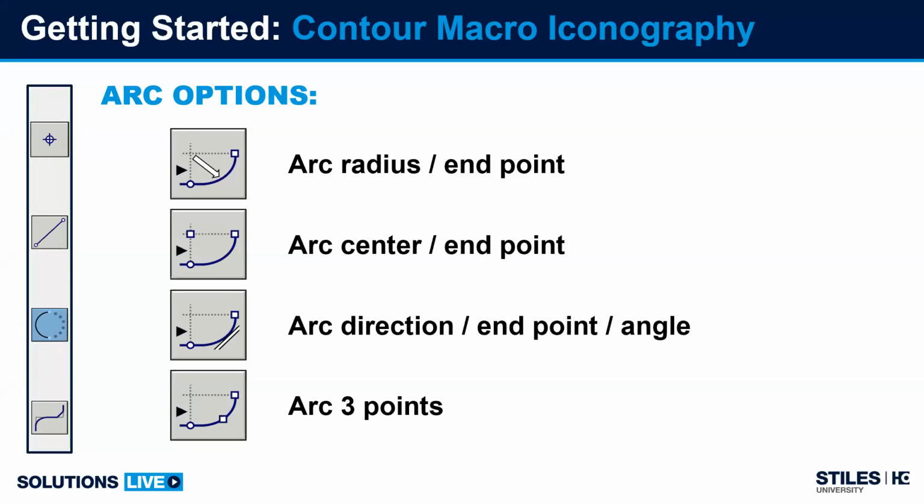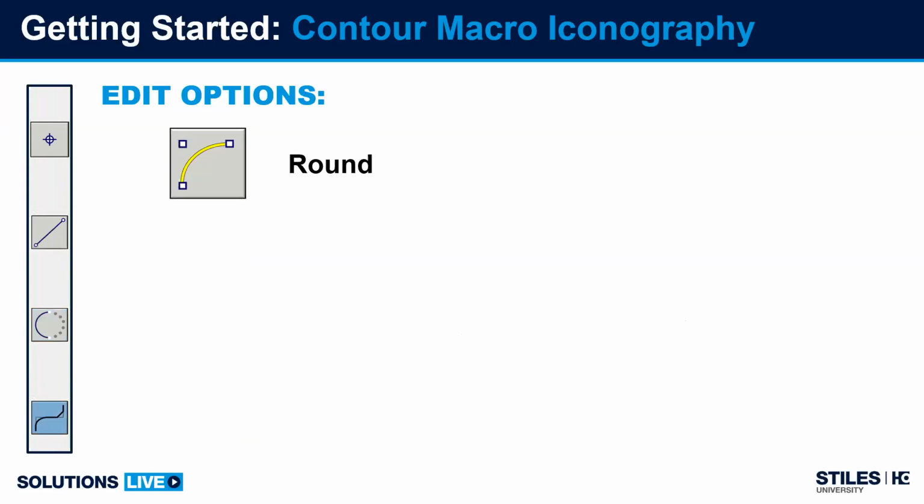Along with that, the third option, what is the direction of the arc, clockwise or counterclockwise? What's the endpoint? And what is either the starting or ending angle? Again, if you know the starting angle, that's great. If you know the ending angle, but without having to calculate those, we're back into the first or the fourth arc. Now, again, we can do Z-axis moves in an arc.